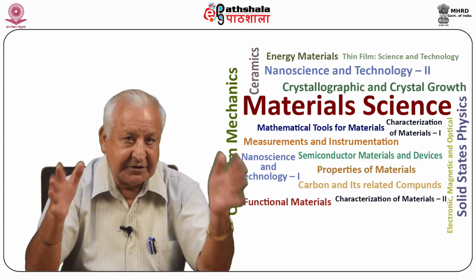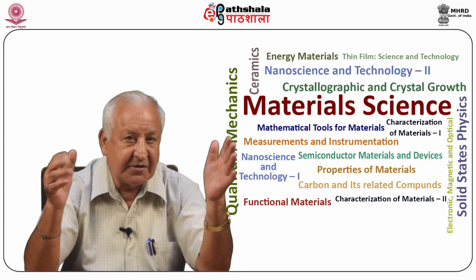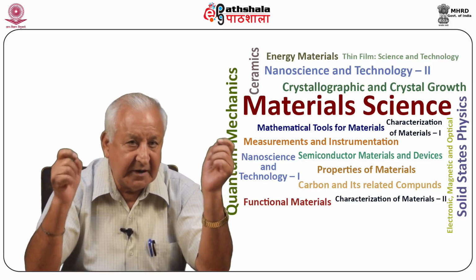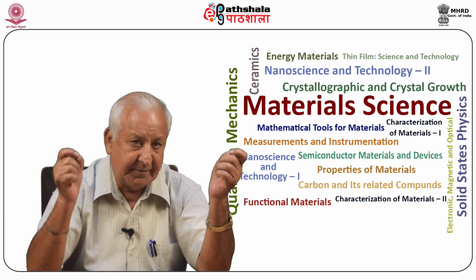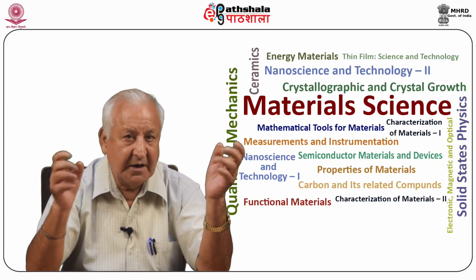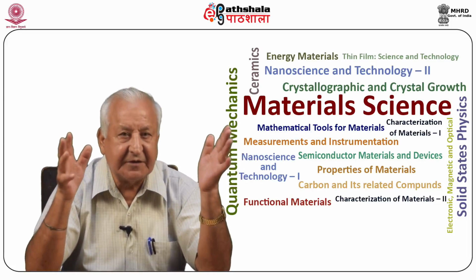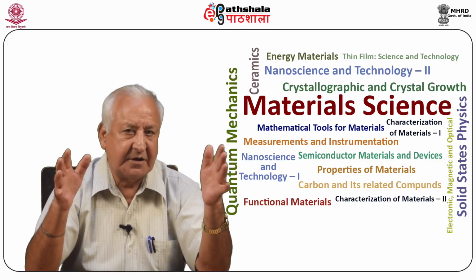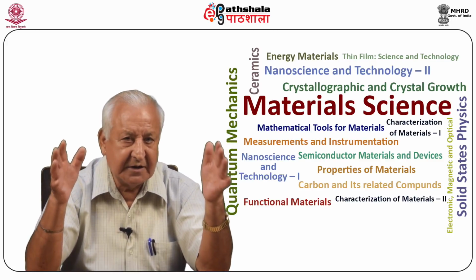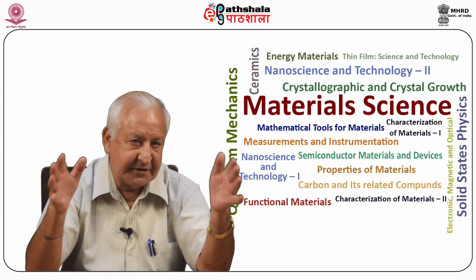In an actual crystal, this difficulty does not arise, since the material consists of atoms and is not a continuum. On the other hand, the stresses in the immediate vicinity of an actual dislocation will also be large, and Hooke's law is not valid in that region.